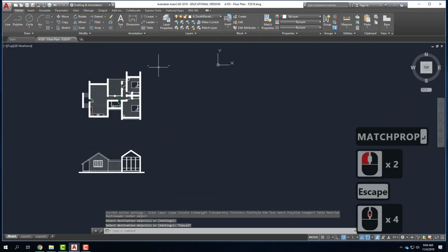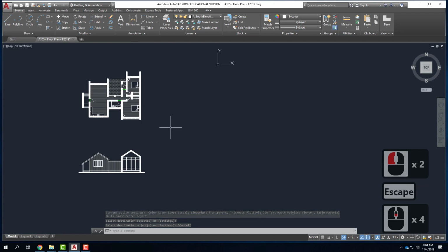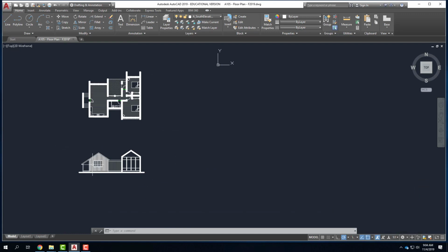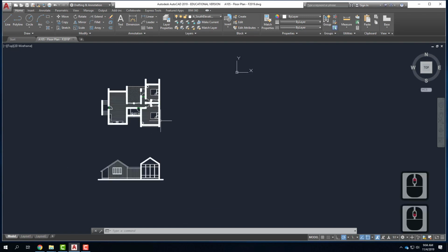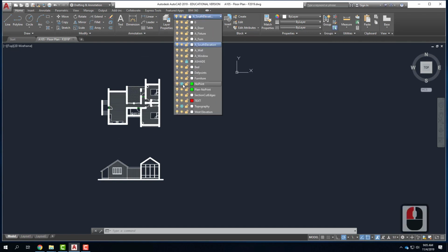But it's time to start working on the next elevation over here. So I have this elevation done. I've assigned the line weights. I want to move on to the next elevation. So when I start to move on to the next elevation, there's a relationship, obviously, with the plan and the elevation, but also with this elevation that I've already drawn. So this elevation happens to be a really simple one for me to draw. There's not even a window on it. So I'll do that one next. So when I start to create this, at this point I'm going to switch back into my no print layer.